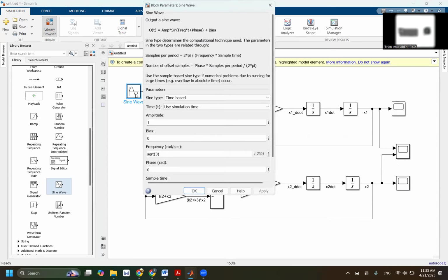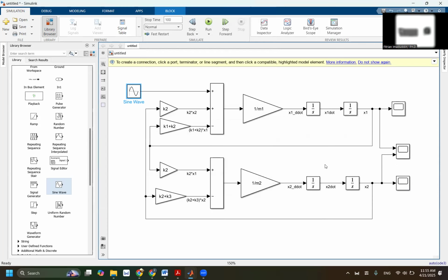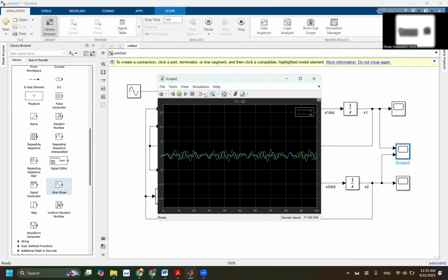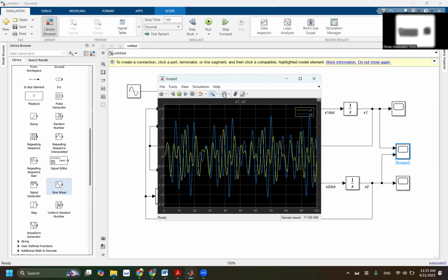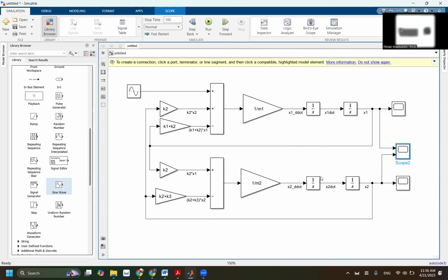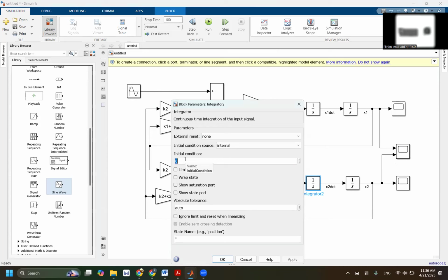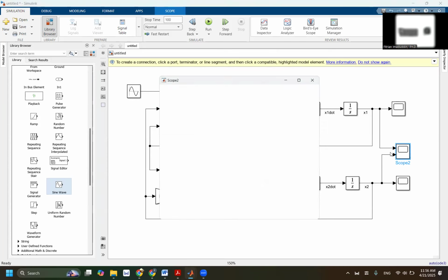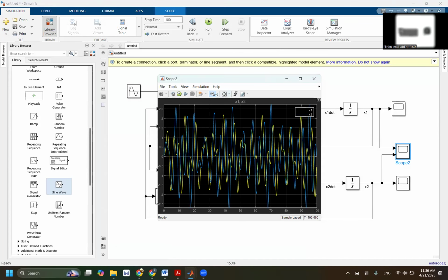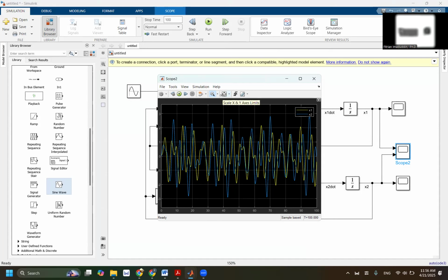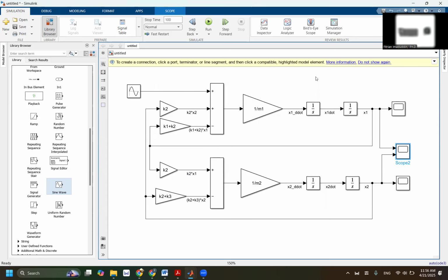Okay, now I'm going to change this to a somewhat more friendly frequency, in between 1 and 1.7. But at the same time, I'm going to put initial conditions. So we have a combination between force and initial conditions. You can put velocity initial conditions as well. Put the second one, say 1. This is what happened. The more variables you put far away from the eigenmode, the more chaotic it seems to be.